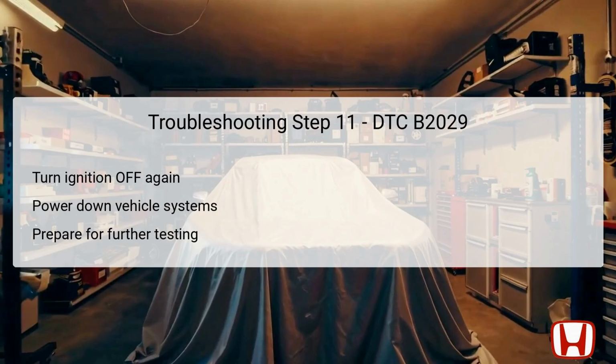This action is important as it ensures that the vehicle systems are powered down fully before executing any further diagnostic check procedures. Powering down the systems can help with eliminating any residual charges or pesky glitches that may affect continuity testing or other diagnostics in later steps. It prepares the technician for a clean start in the next procedures, contributing to a more reliable diagnostic process. As with previous steps, ensuring the vehicle is powered down serves to protect both the technician and the vehicle's electronic systems while further assessments are made.